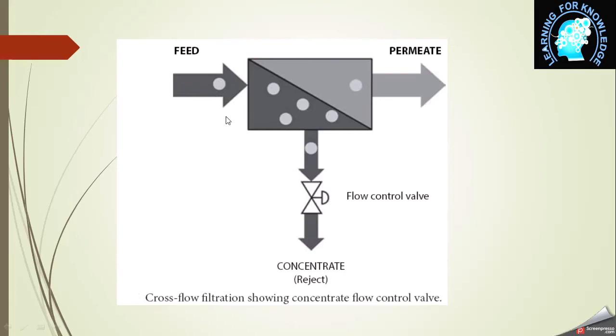So these are basically the two processes. This cross flow filtration process is a better process, because unlike dead end filtration, which is a batch process, it is a continuous process. But after some time, when a lot of solids, scaling and fouling happen on the surface of the membrane, we need to replace this membrane and stop the plant. In the next video we will continue and describe further the membrane process, or you can say purification of the water.